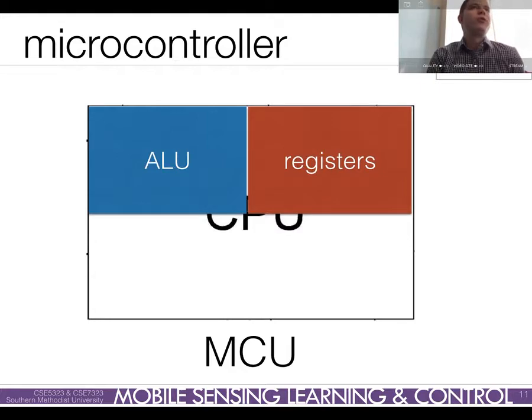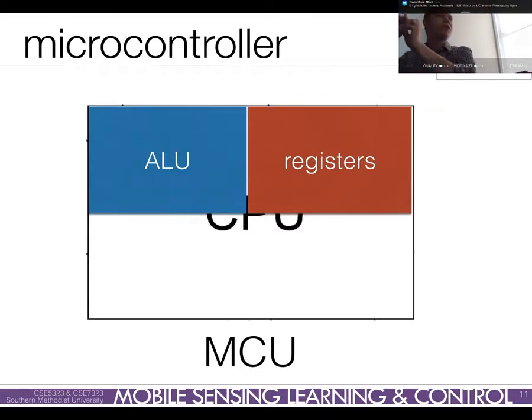Inside of a microcontroller, the registers control all of the operation. So when you go through the datasheet, it's nothing but here's the name of a register, here's what happens when you set the different bits in it. Each register is 8 bits, usually, and each bit controls something that the microcontroller does. So if you set this specialized register, all of a sudden something starts happening, because you've got all these peripherals that read those registers and then do stuff. It's all of the control logic for this microcontroller.